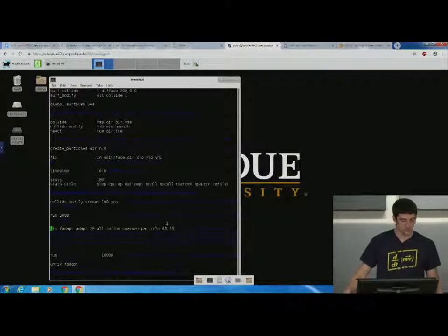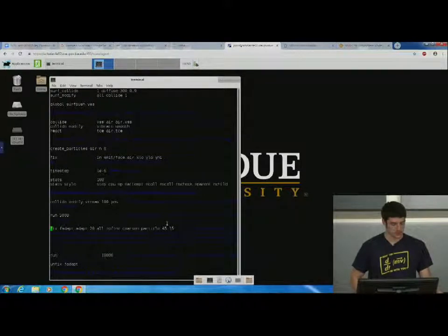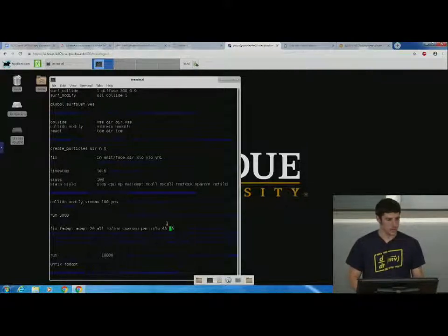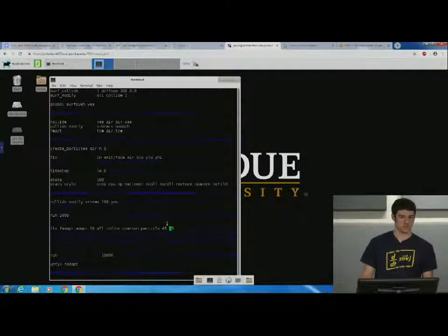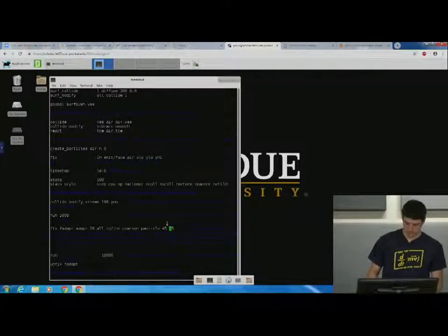So in this case, we're saying we're going to adapt the grid every 20 steps, and we're going to refine and coarsen according to the number of particles in the cell. If there's more than 45 particles per cell, we're going to split the cell. If there's less than 15, we'll coarsen. Well, this is a nice tool, but it's not a perfect thing. It's sort of limited in what it can do. It tries to split cells, refine and coarsen, combine with a bunch of other cells. So you can't really rely on this to do everything perfectly, but it certainly does help the problem a lot.